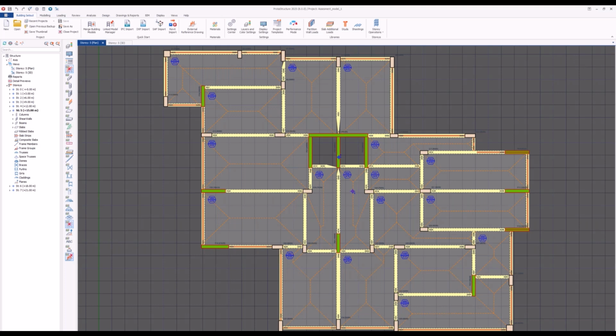And we also have nonlinear time history analysis. We automatically calculate all the material nonlinearities, and we can communicate these nonlinearities to the OpenSees, and we perform all the nonlinear analysis in the OpenSees, and we collect the results back, and we send them to a post-processing, and we create the assessment report. I can talk about this assessment maybe in another webinar because it's a very detailed topic by itself.